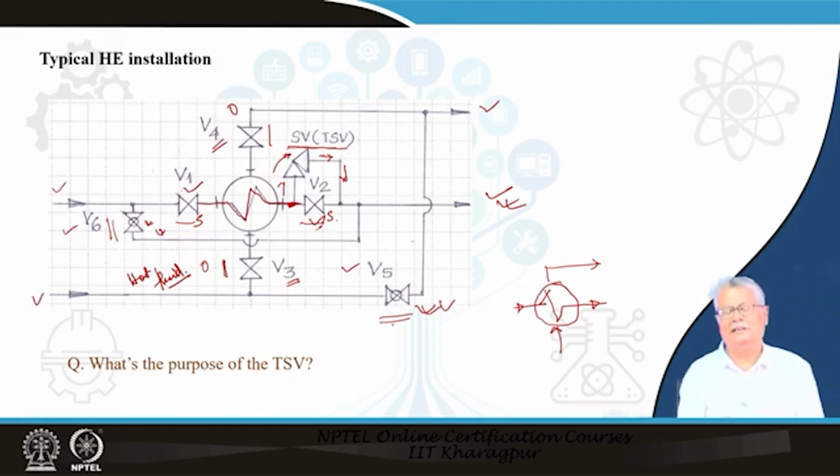So, I believe you now get why such safety valves are called thermal safety valves also. Remember that thermal safety valves do not have any relationship with thermal actuation of the safety valve. No, it does not. It is not like a pressure cooker safety valve. It is just a common safety valve which is used for releasing the overpressure due to thermal changes.